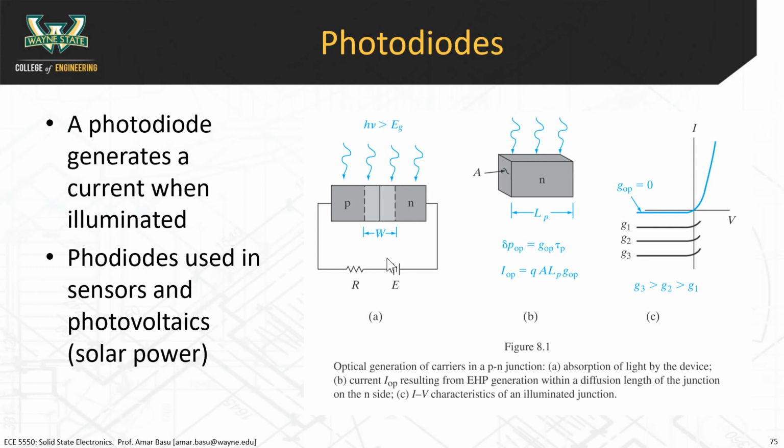Let's just say, for example, an N-type material. You illuminate it uniformly. This is one of the questions on your exam. You get carriers, and you turn the light off and they recombine, right? Was there any current? No. If you uniformly illuminate a semiconductor, there's no current. So that's the thing: there's no current that can be generated just from a single type material.